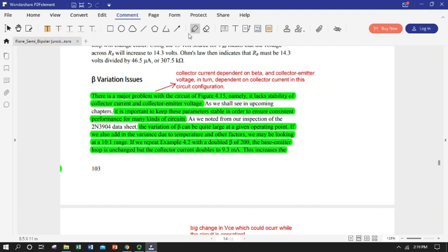Okay, we did also at the same time mention there might be some instances in which we don't want to use beta to control the collector current. We might want to design the circuit outside of the transistor such that it limits the collector current instead of beta. Now, the first question you might ask is why? We went to a lot of trouble to get this magnificent little semiconducting device that has this enormous current gain. Why would we want to throw it away, or any part of it?